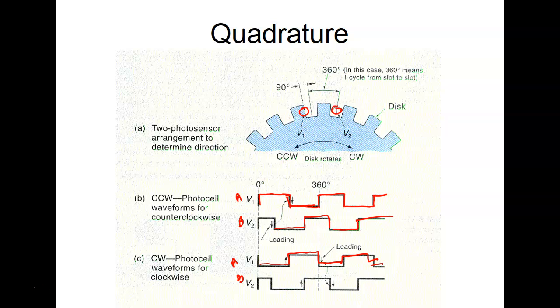They call them absolute encoders, but they're not really absolute encoders. It's just that they appear to be absolute encoders to the controller. So what's the advantage of quadrature encoders? Not only can we use them to sense position, we can use them to sense which direction they're going. That would tell our counters to count up or count down from 0.